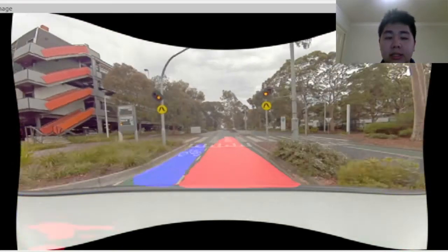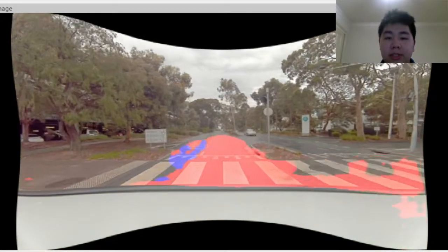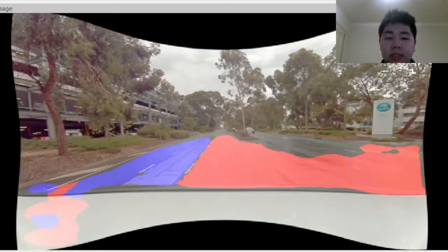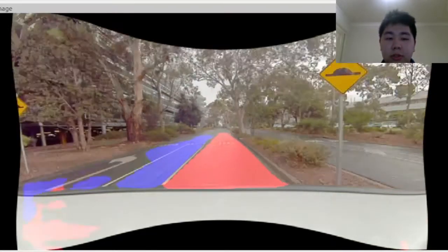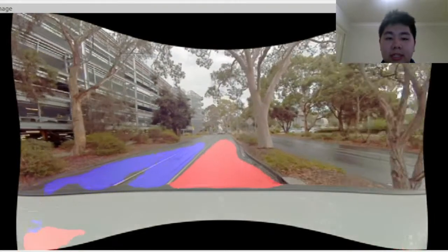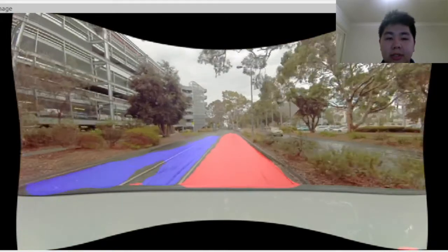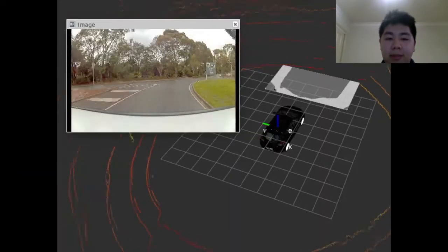The detection system is a subset of supervised machine learning, which is defined as image segmentation. This processes the camera feed through a fully convolutional neural network pipeline and classifies each pixel into one of three different categories: drivable, alternative, and none.